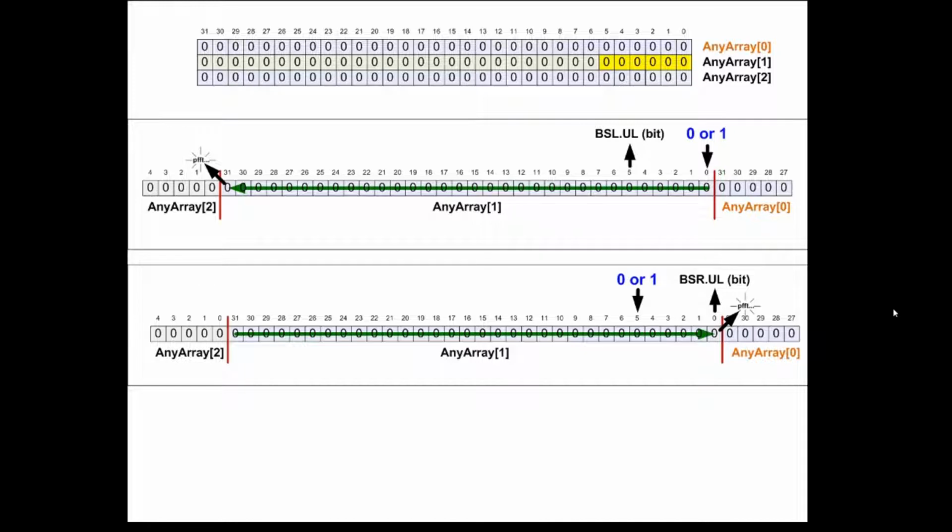And then on the bottom, you have the bit shift right, and the only difference between a bit shift left and a bit shift right is the position of the unload and where new values are pulled in. So if you're going left, new values are always pulled into bit 0, and whatever the length is, in this case 6, they're unloaded at that position. But they keep on going across that double integer until they disappear when they leave bit 31.